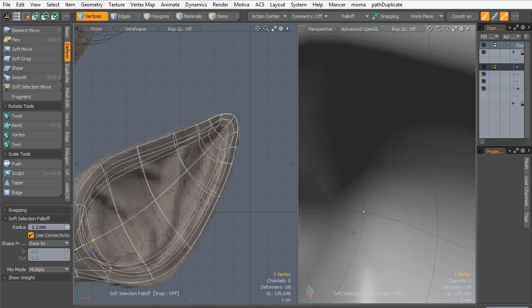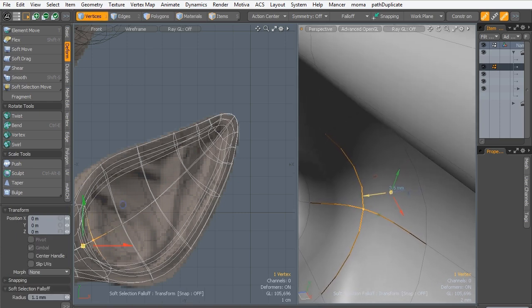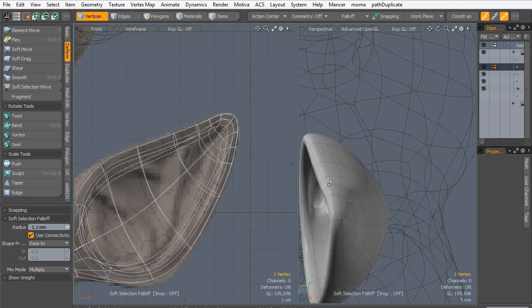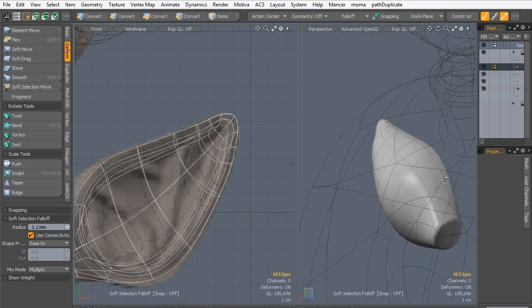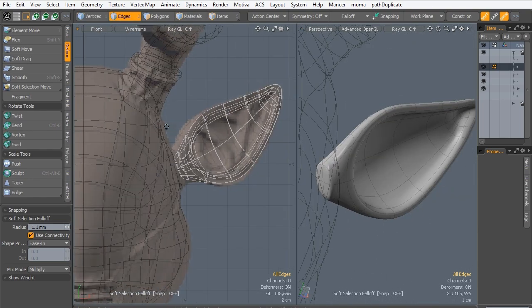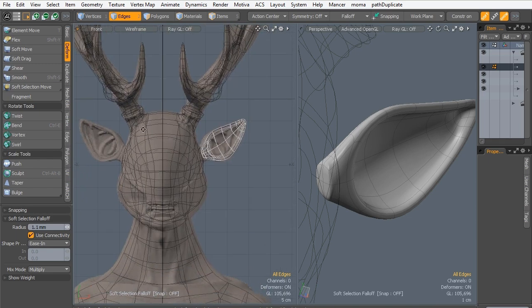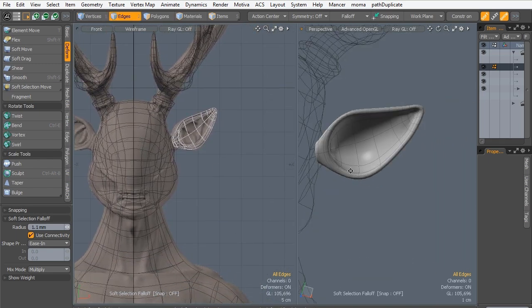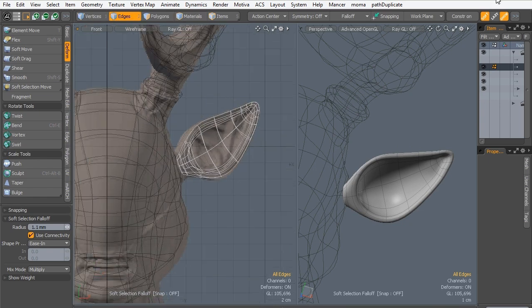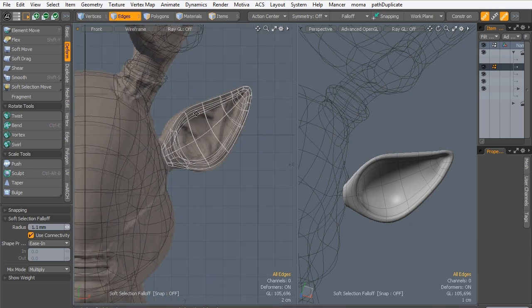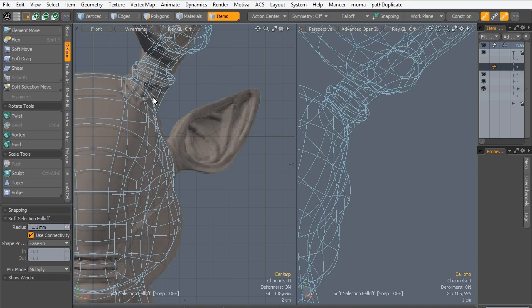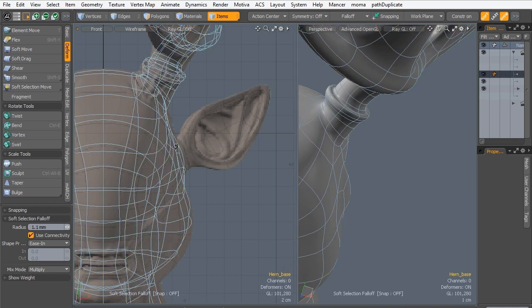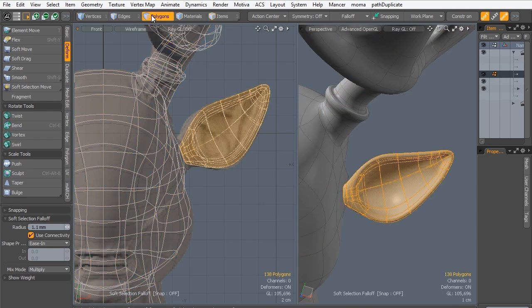As you can see, we've got overlapping geometry here, so we need to select these vertices and move them to the front, because they would give us sculpting errors and also rendering errors. Right? So, with this done, now we can just copy those polygons. So, copy this, Ctrl C, I go to the character layer and paste this here.